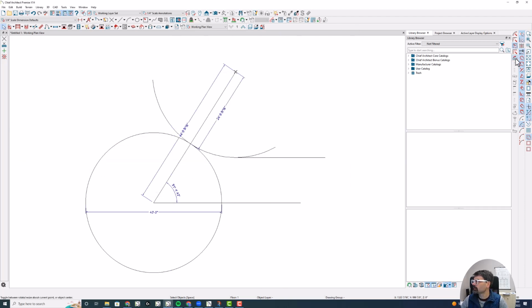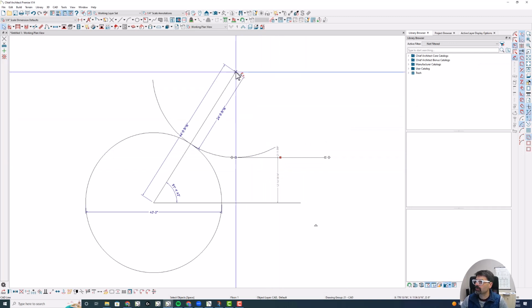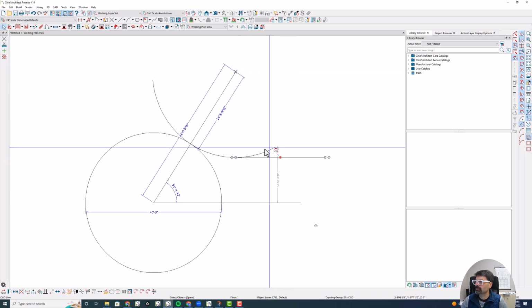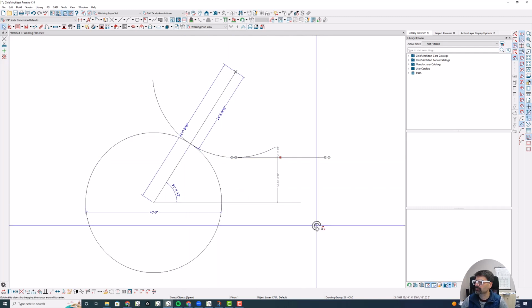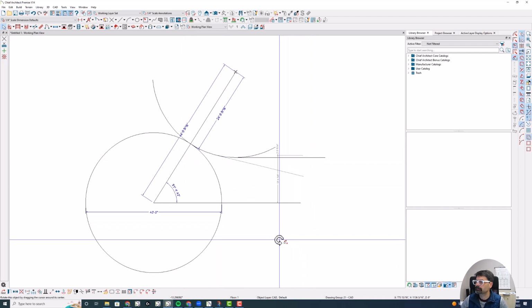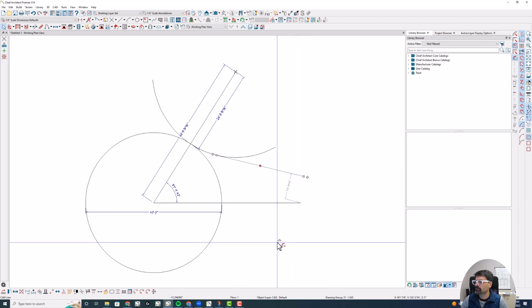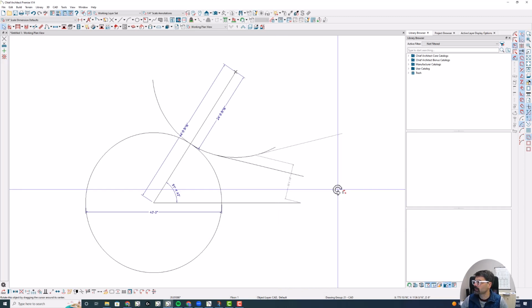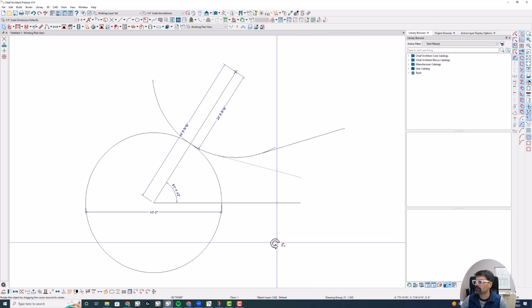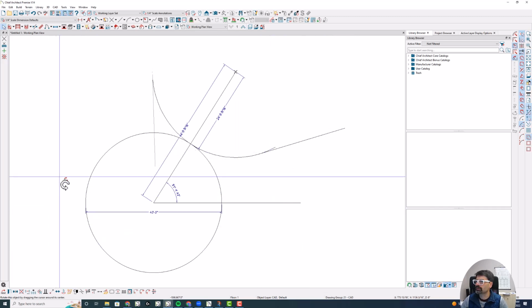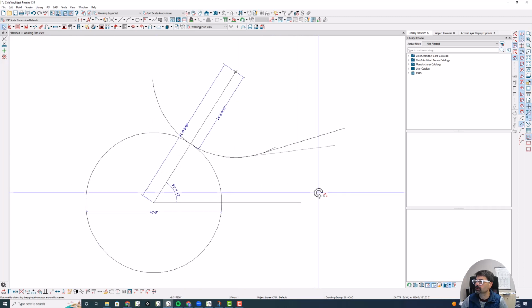Anyway, I'm going to turn this on by clicking the toolbar right here, rotate, resize about current point, selecting my arc, and that's going to rotate about the center of this arc now. So no matter what angle I change this at, I know it will remain tangential to the arc. I hit Control, that temporarily overrides my angle snap, so I could take it up this way. I could take it down this way. I could rotate it all around, and I know that's constantly tangential to the arc. So let's do it like so.